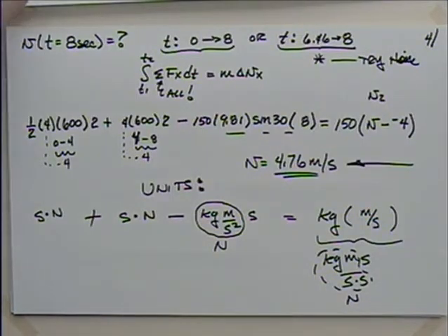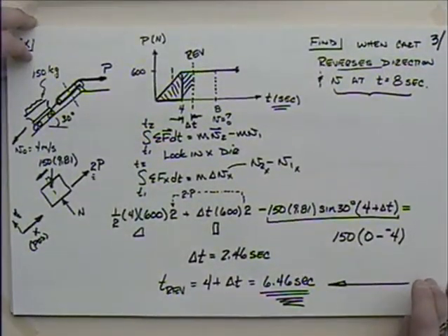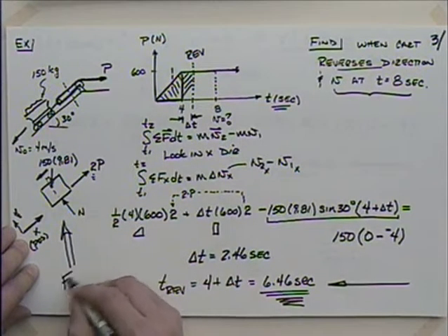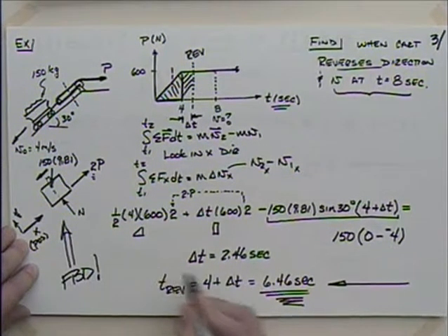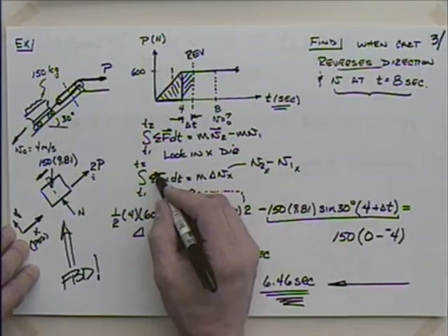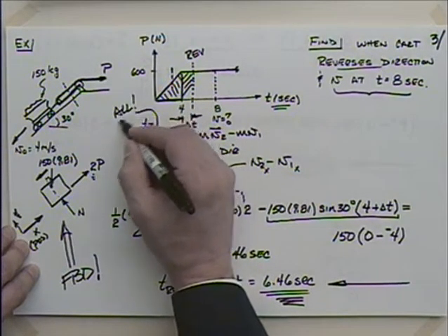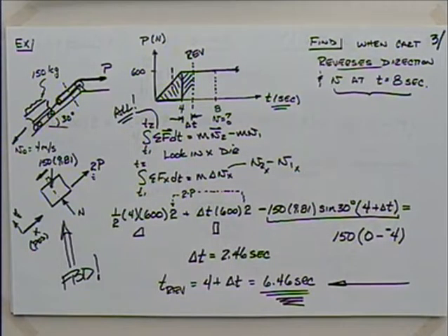Well, to sum up this problem, the most important thing is the free body diagram. Because when you do the forces, this summation here, this is all of them, and you got to get them in the right direction. Okay. So that'd probably be the biggest tip that I would give you in this. Questions with that? Well, that gets a good starting point.